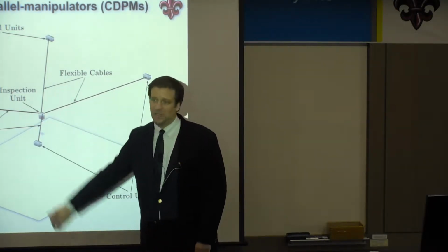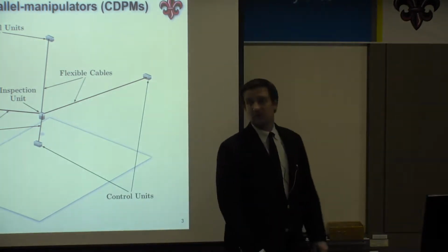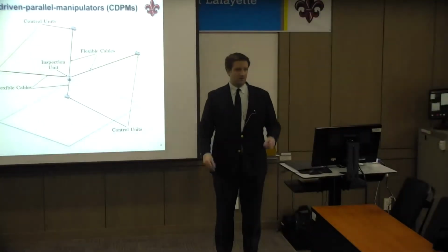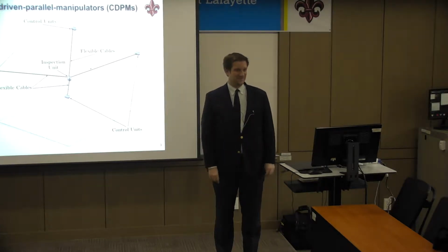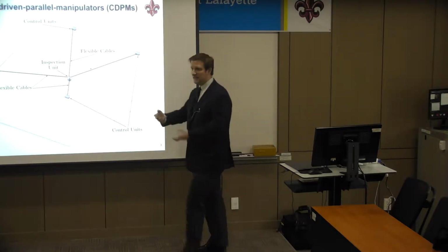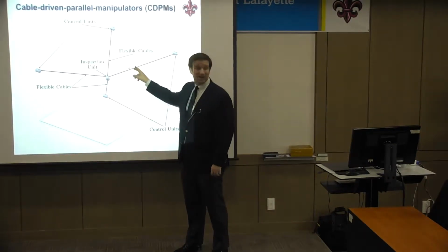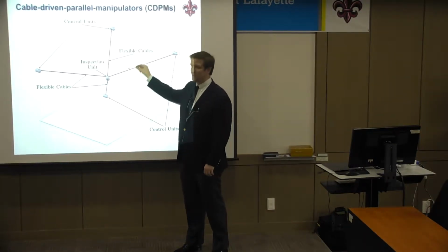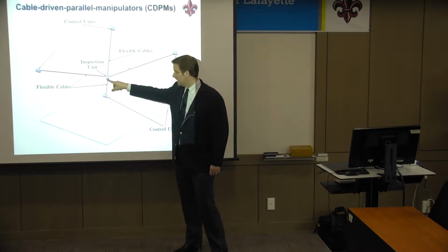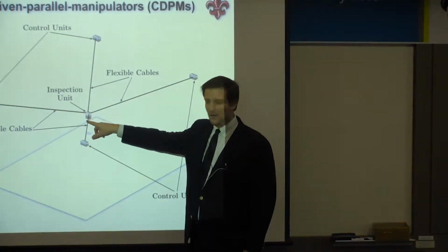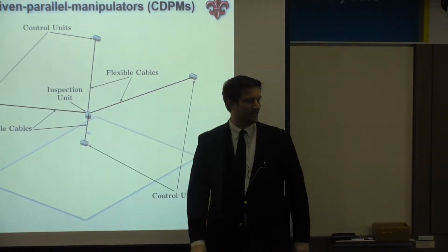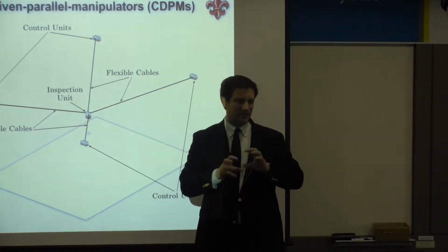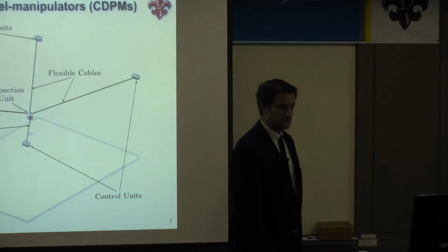But these cables actually can be tens or even hundreds of meters long. So even if it's a steel cable, you can get a little bit of stretch if it's 100 meters long. Right? And then basically, even though it's a steel cable, it's still a string. So we can get some vibration, string type vibration in these cables that cause vibration here. And then depending on what I'm doing here, I'm just hanging from strings. So I don't have so much way to kind of control what I'm inspecting.